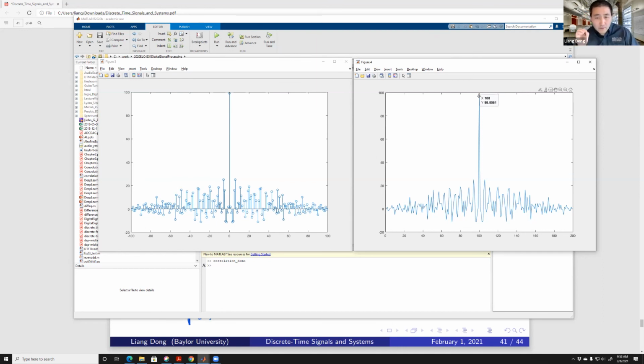Remember the white Gaussian noise we discussed last time. When I do the frequency spectrum, it gives me a constant over all frequencies. Now, the autocorrelation of white noise means that two samples, W1 at time 0 and W1 at time 1, are random variables that are not correlated at all. Each one picks up a random number by itself, so they have no correlation whatsoever across time. Therefore, the autocorrelation function looks like that.